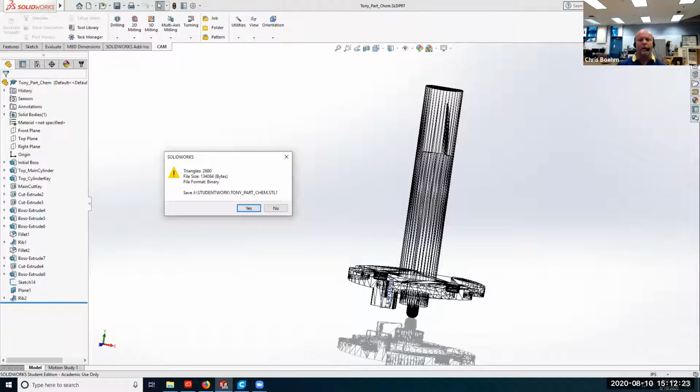So if we were to save it as that, do you see that essentially what has taken place here is literally the geometry has been triangulated. And so it's almost a constellation of points that the system is going to be providing ultimately to the printer in the form of G code. So it's just telling the printer X, Y, and Z go from there to there to there.